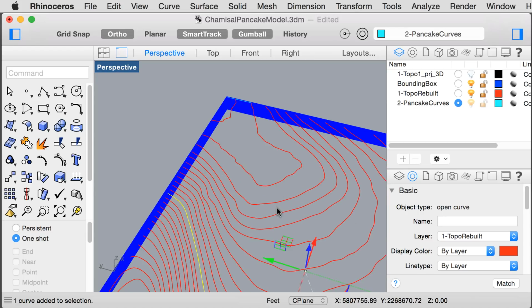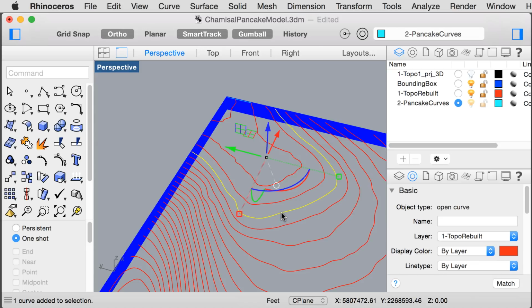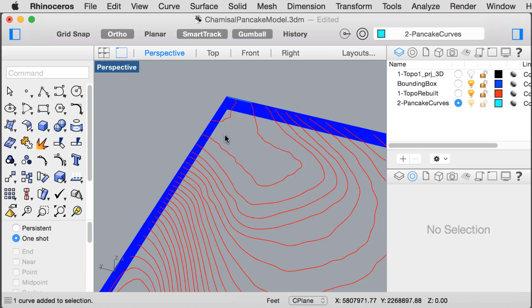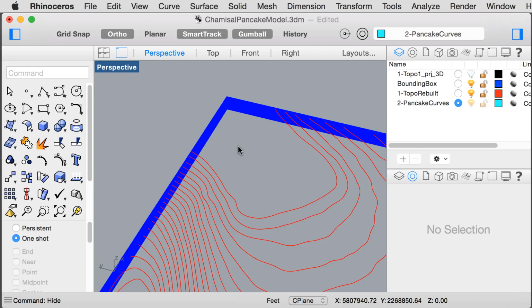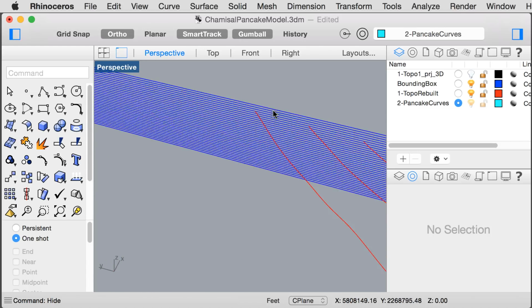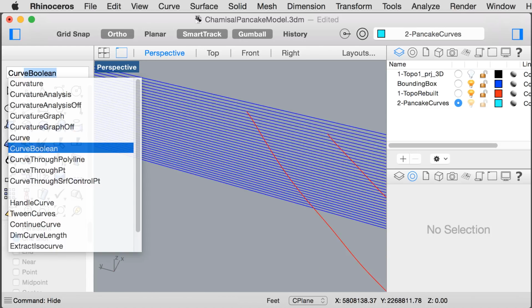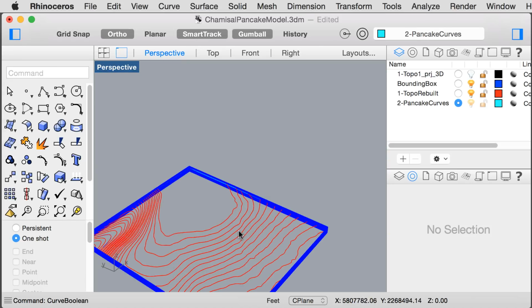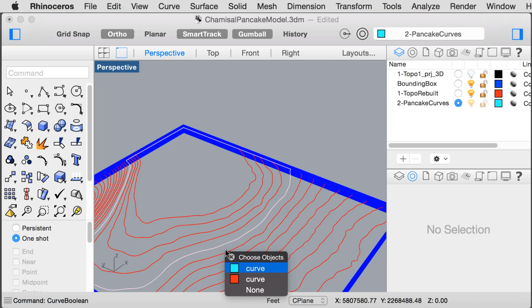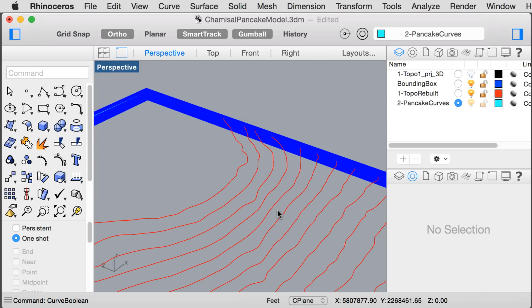One thing I find helpful is that you can start to go a little cross-eyed. So as you finish curves, it can be very helpful to hide the ones that you've already done. So we've completed these top 3. Select those top 3, type hide to get them out of the way, and that enables us to move a little bit easier. Okay, I have just reached the point where things change a little bit. Let me hide all of these that I have completed.